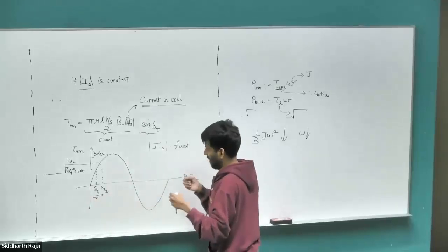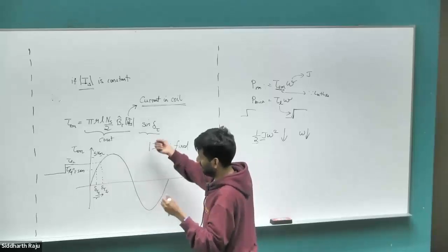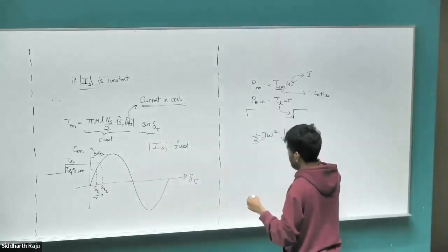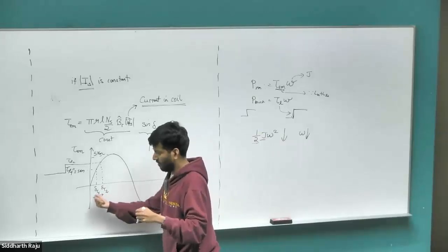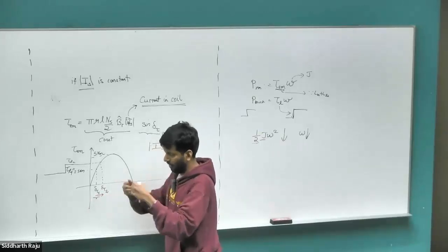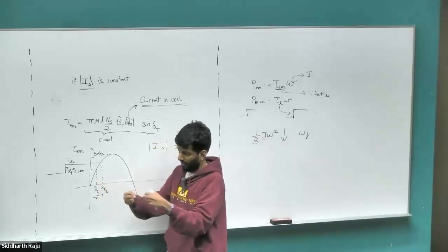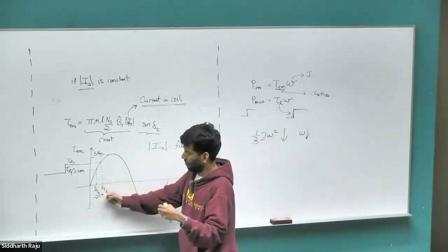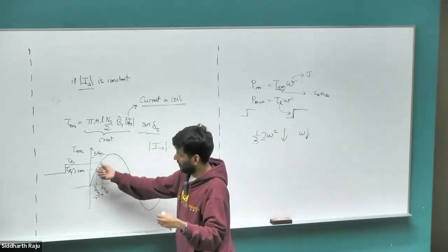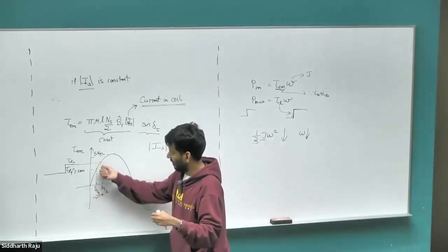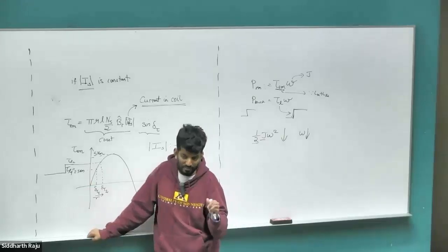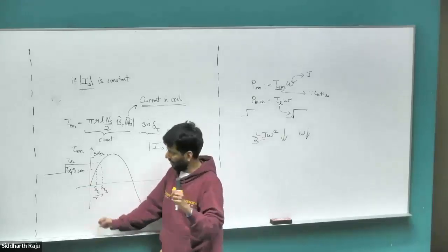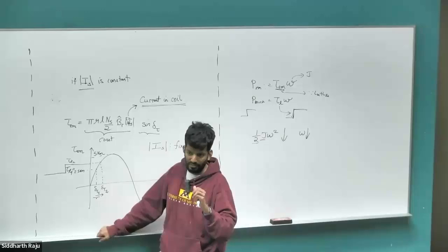So the same thing is going to happen here. And the equation is exactly stated. So the speed would start to come down. If the speed starts to come down, you're lagging behind. So the separation between you and your friend in the case of running, or between the two vehicles tied together, is going to increase. And it's going to go to a new point where the electromagnetic torque generated is equal to the load torque that's being requested and can be sustained at steady state. At steady state, it will reach this new point around there stably.